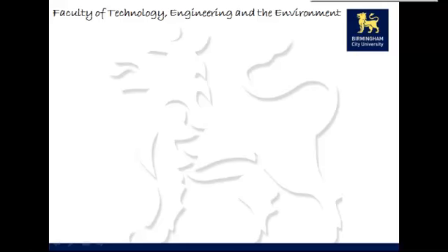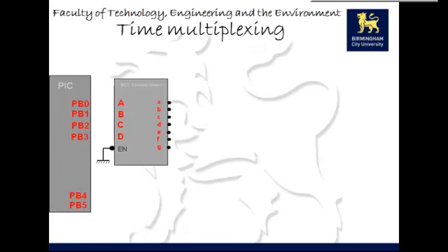I'm just going to start back where I finished off. So this is the slide that I finished on. We've got a microcontroller. 4 bits of the microcontroller, port B chosen randomly, are connected to the 4 inputs of the BCD decoder driver integrated circuit. Now this decoder driver has a permanently low enable, and we'll permanently enable the IC by taking that control line to ground.